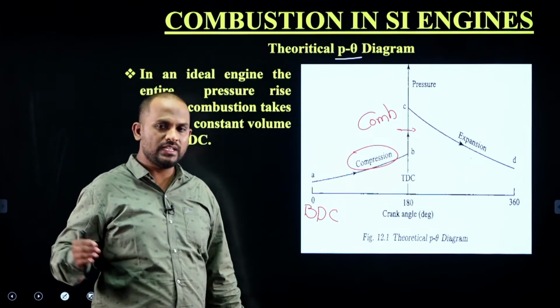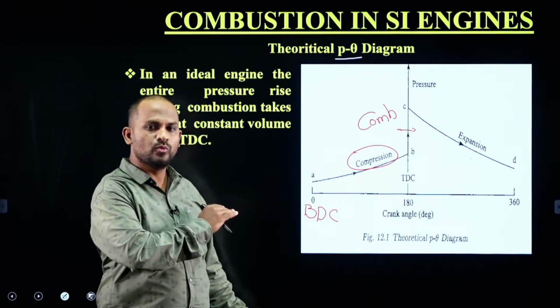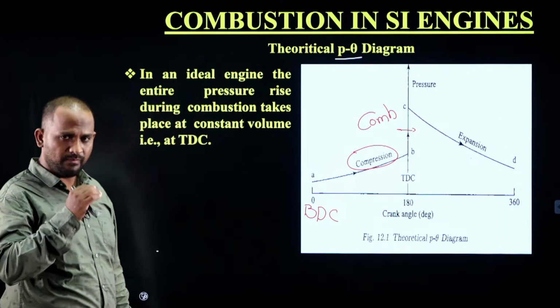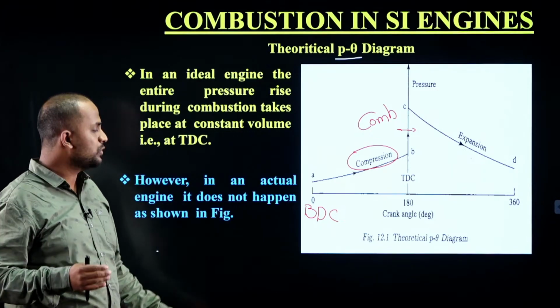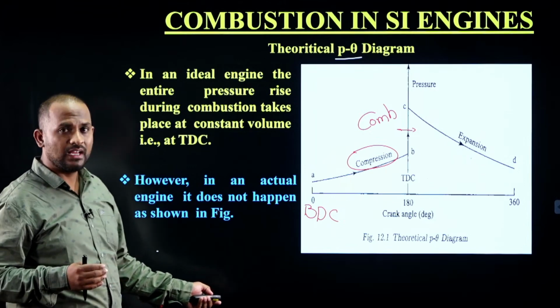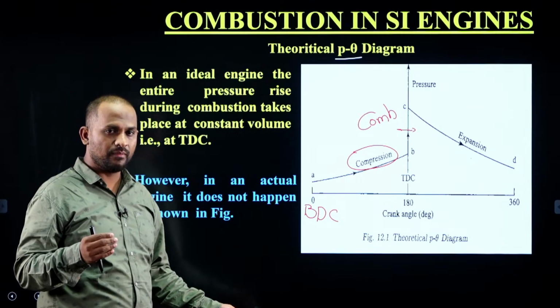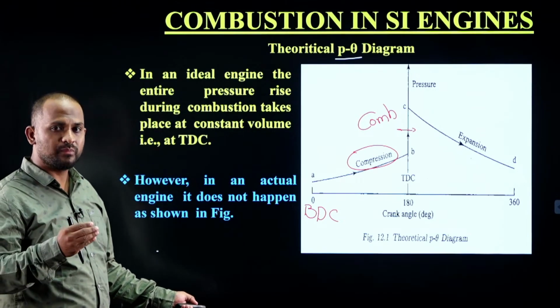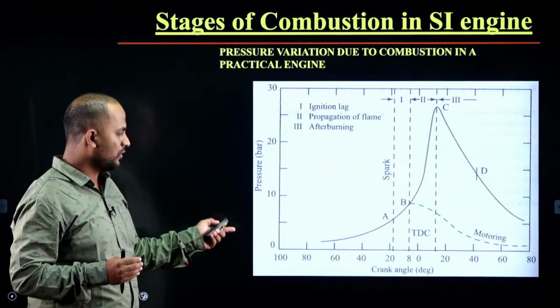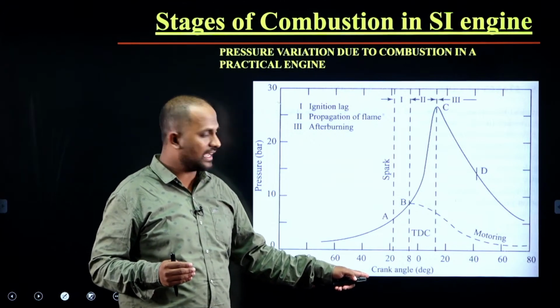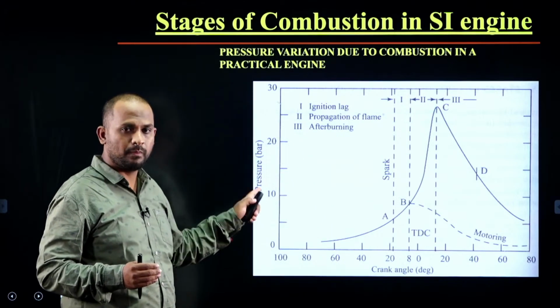Now this is a theoretical P theta diagram. In actual engines, it won't be like that, in a smooth and uniform manner. The entire process will be divided into stages. So let us see the actual P theta diagram, that means the stages of combustion in an SI engine. Now this is a figure where the x-axis is crank angle and the y-axis is pressure.